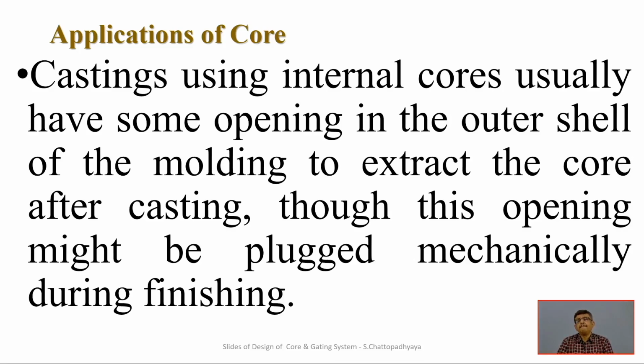So some outlet has to be there where the collapsed core sand after the casting can be taken out, and those plug holes may be plugged with some external additions after the casting, and that is sometimes necessary. Otherwise the core sand will remain there. So the hollow structures are not emptied, and we need to empty those hollow sections through extraction of the core sand from some outlet.